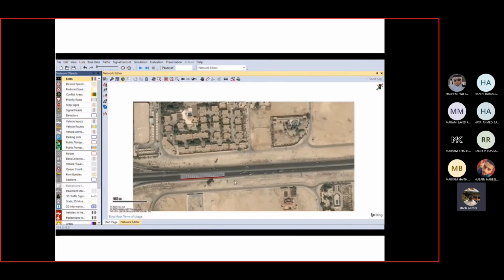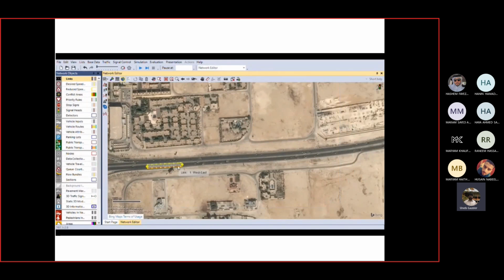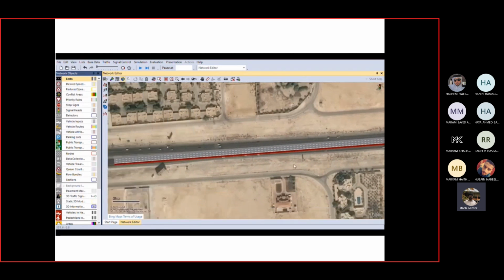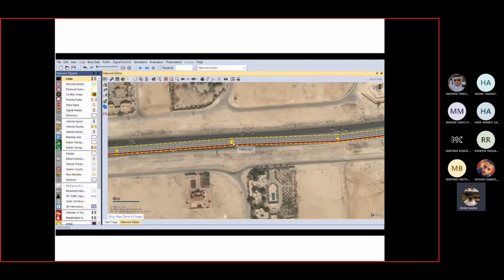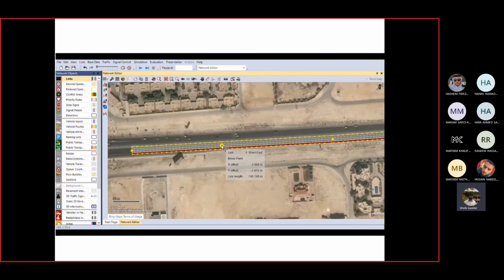And what we'll do now is we'll zoom out, you'll click on the road and you'll drag one end all the way to the end of where you need your road to reach. Now, if you look, the alignment is not exactly correct. So what we do is you'll click on the road first, right click on points on the road to add bending points. So now using these points, we can just shift the road and align it perfectly. Just drag and hold and realign your road.